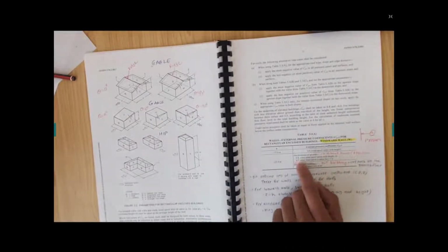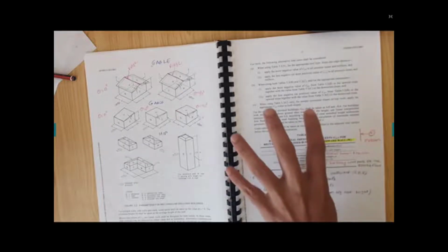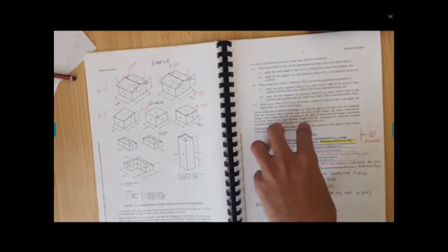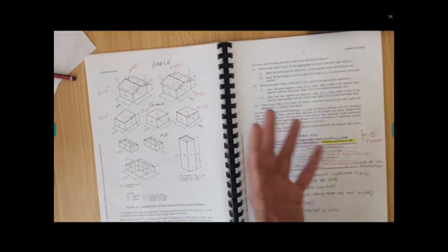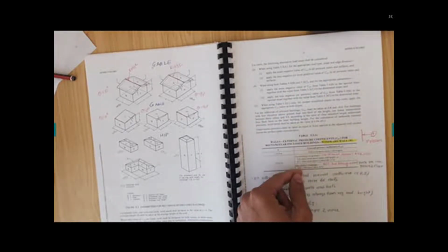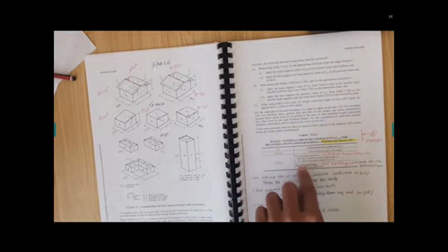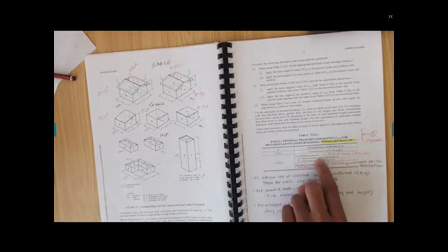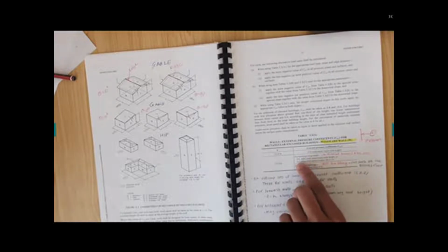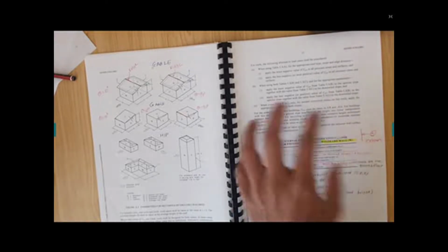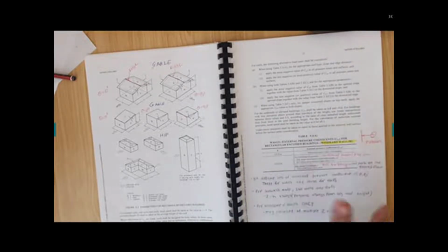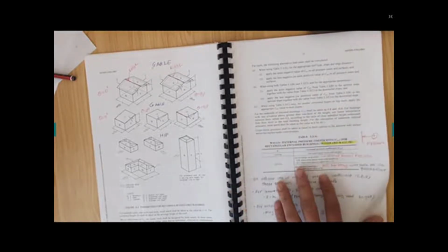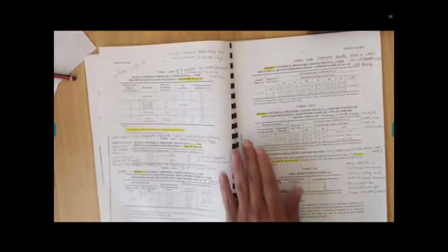And please keep in mind that you have this 0.7 most of the time in our course. If you don't use these tables, keep in mind CPE is 0.7, right? Because you have 0.8, and 0.8 is not applicable. This is for tall buildings and normal structures. We take it 0.8, but our wind does not vary with height, so we always take it 0.7. So if someone says, what is the CPE value for windward wall, 0.7, okay, for our course. So that's 0.7, quite easy.